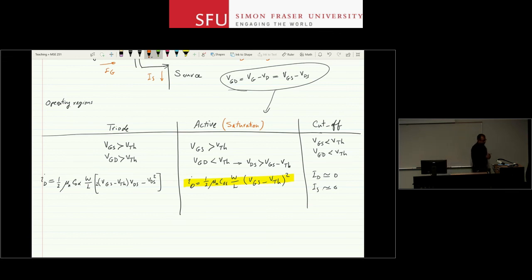We didn't want the transistor to enter saturation. In MOSFETs, if you use that terminology, you want the transistor to be in saturation region if you want a current source. And that can be a bit confusing. So to avoid that confusion, I'm going to call it active region. But when you refer to your book or other references and you see that they say the transistor is in saturation, it means active region for MOSFETs. It's not the same thing as BJTs.